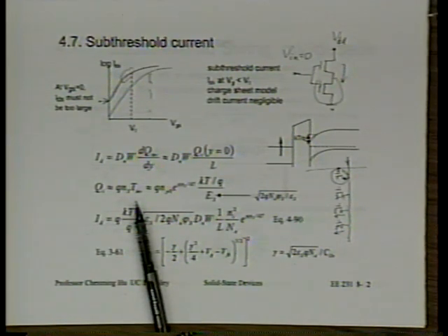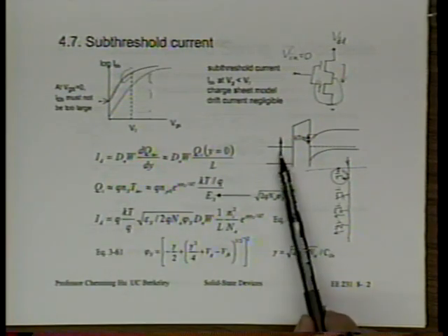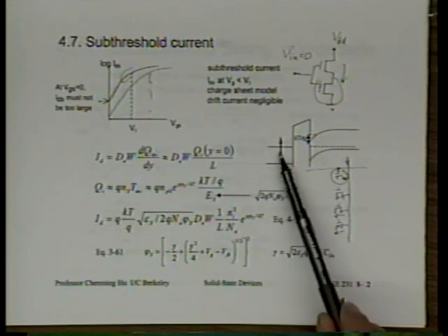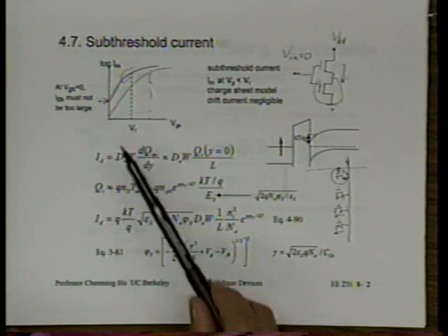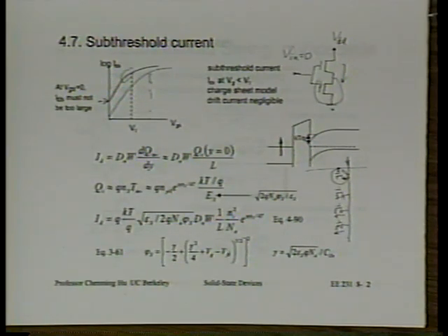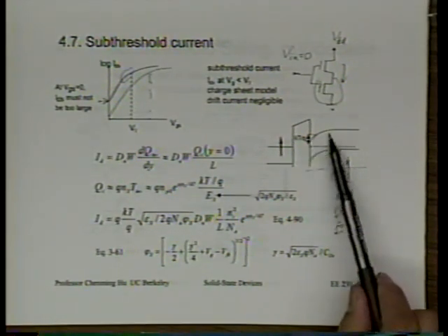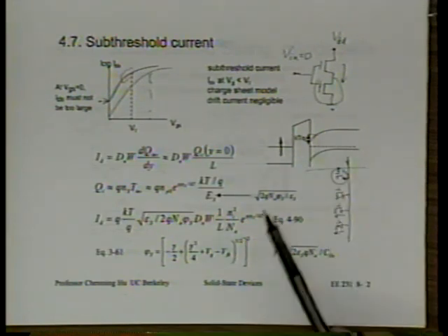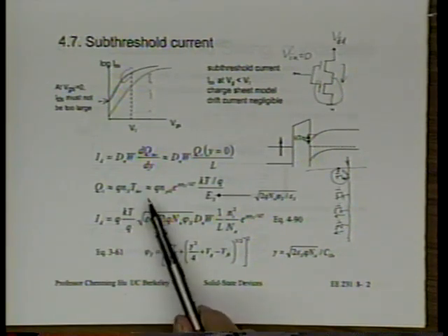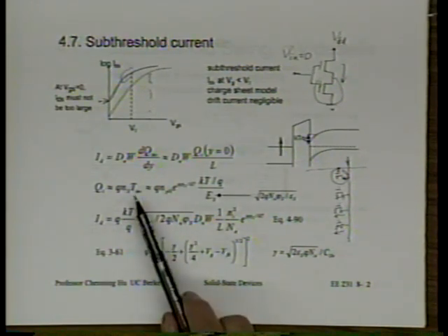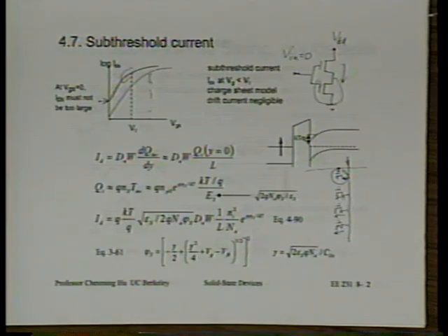But that thickness is actually a strong function of the gate bias. When we apply a gate bias very close to VT, or right at threshold, or in this case actually below threshold, of course the electric field in the substrate is not as large, and the inversion layer is expected to be thicker. So today we're not just going to assume this to be 20 angstrom. You will see what we're going to do. But in strong inversion, if you say it's 15, 20 angstrom, that's a good answer.